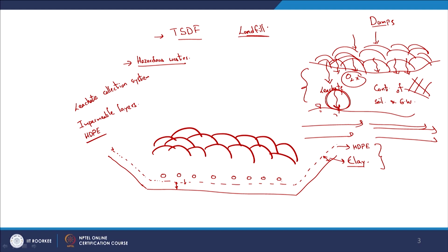Because if you do not coat the perforated pipes with this geotextile, your silt and such can block these pipes, and the leachate will not be collected. So your perforated pipes will be coated with this geotextile, and here you will have relatively gravel and maybe sand layers, a few centimeters thick above this HDPE membrane.